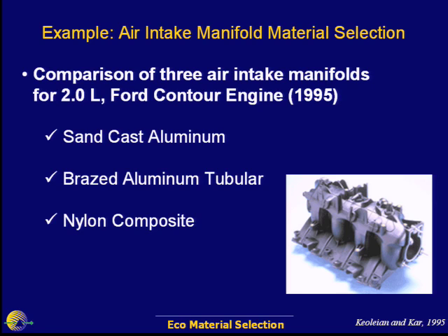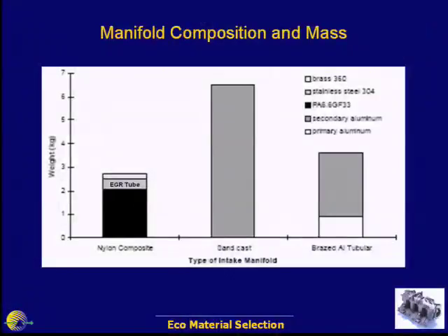What are the materials? Here on the, this is your left-hand side. We've got the nylon composite. Nylon composite is mostly nylon, but it actually needed a different EGR component. What does EGR stand for? Exhaust gas. Yeah, exhaust gas recirculation. Right? Hot gases, probably not the best combination with nylon, so they needed a stainless steel EGR tube to go with this. They also had some brass straps.